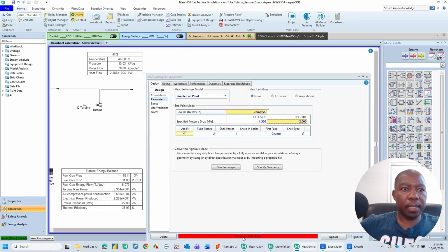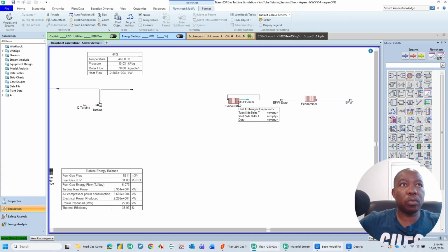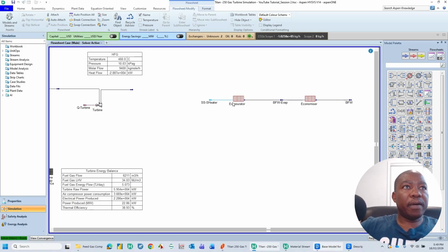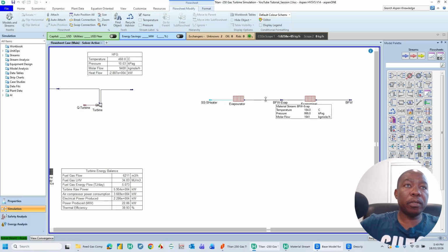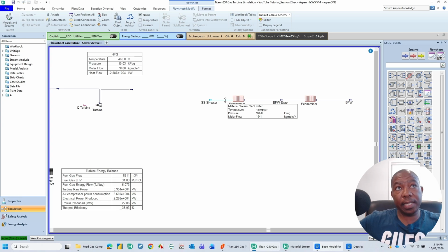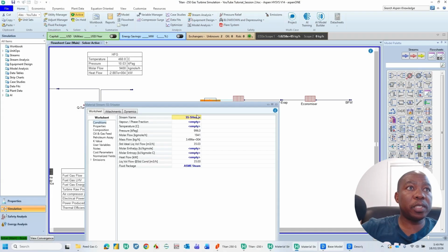And it still says requires a feed stream. That is the hot gas stream that we're still going to come back to. So let's spin this. I'm clicking on it and I press 1 to rotate it. And then we need to specify the conditions on this side, right? What did we say? The temperature coming in here is 184, the saturation temperature. And the steam comes out still at 184, but it has changed phase. It is now vapor. So what do we specify here?